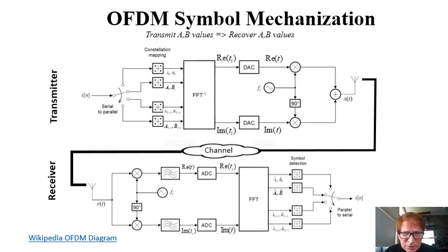The general expression for the number of transmitted bits per symbol time is 2 to the bits raised to a power equals M. We will say more about this equation later because it becomes quite important. For example, 1024 can represent all unique values that can be formed from 10 bits. The S sub n sequence is broken into constant length subsets based upon the selected MQAM. These are then mapped into A and B pairs or symbols using the MQAM constellation layout.